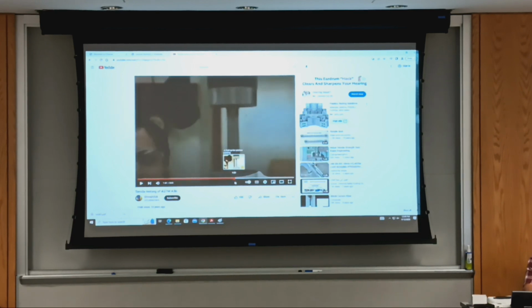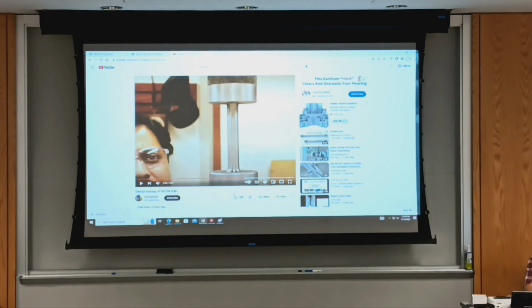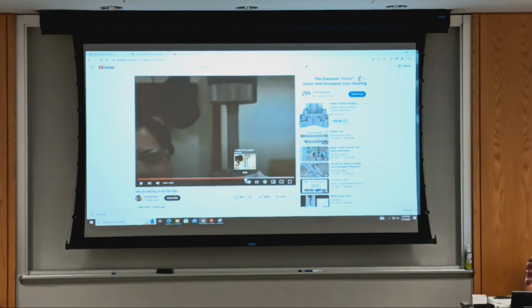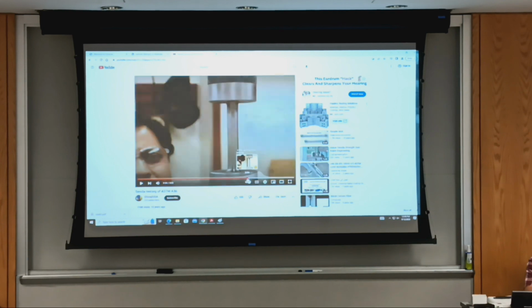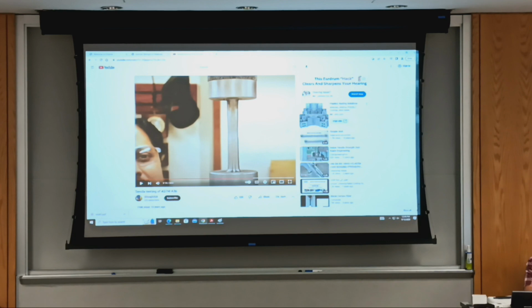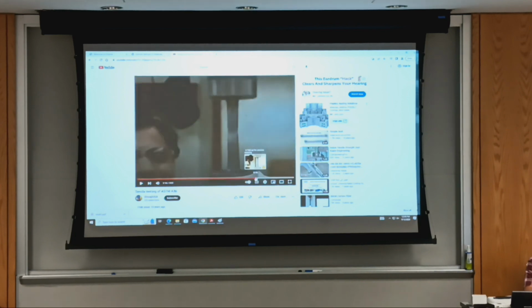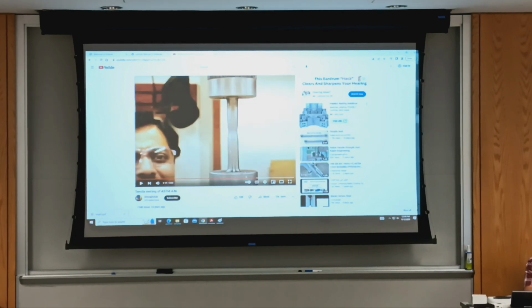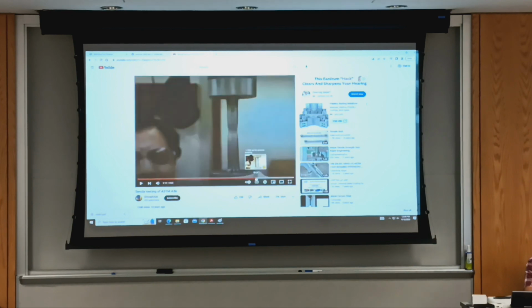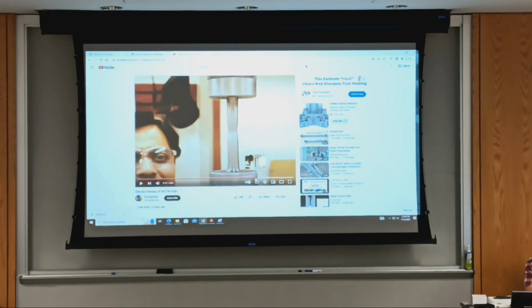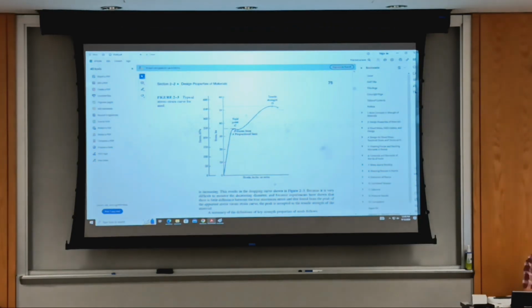Yes, and then it stretches, and then you can see about even, or even, shrinkage, and then there's a neck that develops, usually in the middle, but it's not a rule. It might be some imperfection in the material that makes the neck and the fracture develop elsewhere than in the middle. This is for ductile materials like low carbon and medium carbon steel, and we'll discuss ductility in just a little bit.